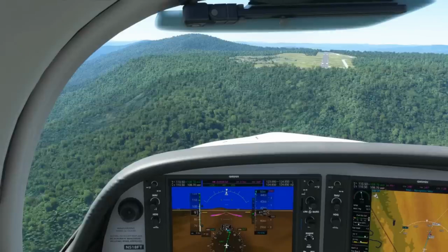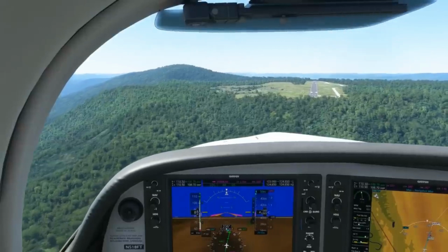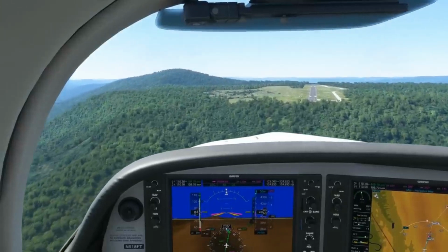The greater the crosswind component, the more difficult it is to prevent weather vaning, especially with a conventional gear airplane. Maintaining control on the ground is a critical part of the after landing roll because of the weather vaning effect of the wind on the airplane. Additionally, tire side load from runway contact while drifting may generate a rollover in a tricycle-geared airplane.